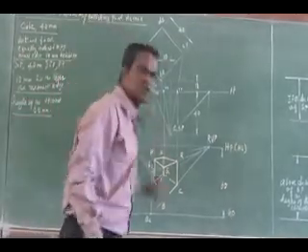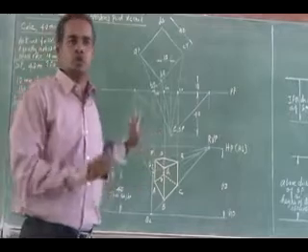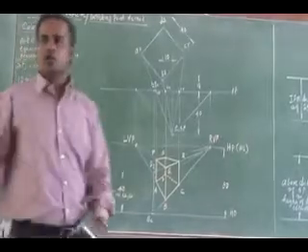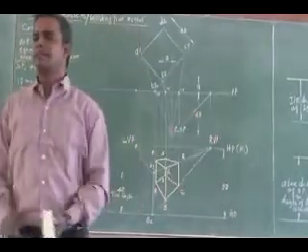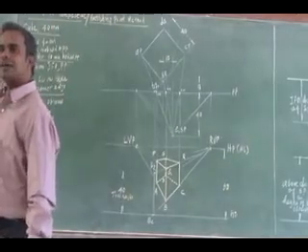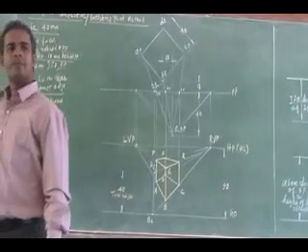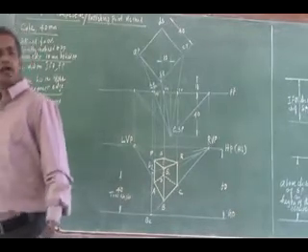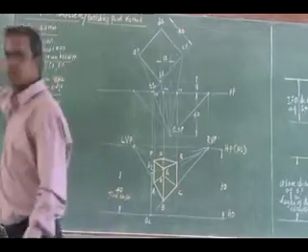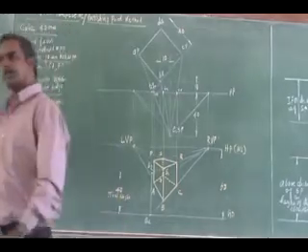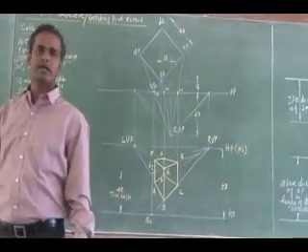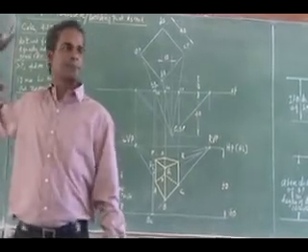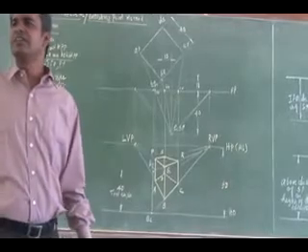Up to this, we have seen square pyramid, square prisms, cube. So problems you may have: suppose instead of the square pyramid in the previous method, if it is a hexagonal prism, you have to draw the top view as a hexagon. The front view will show the edges of the hexagon. Vertical edges you may have 4 edges. That you have to join to the station point as in the previous method. So instead of a square, you may have a hexagon, pentagon also, a pentagonal prism or hexagonal pyramid. So mostly we will be asking in this. Is it clear? You have any clarification?